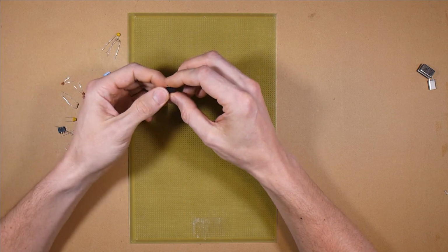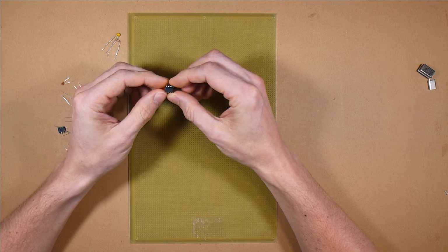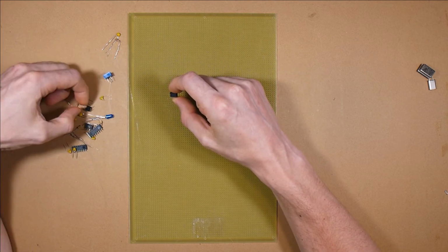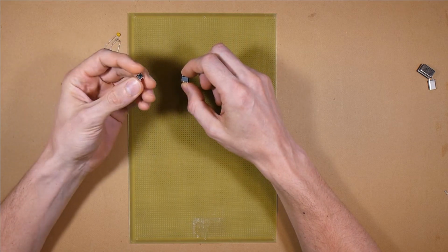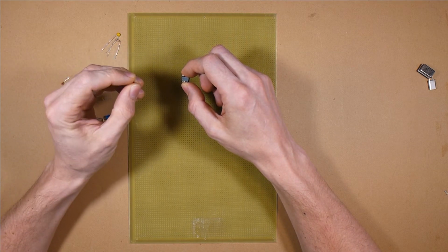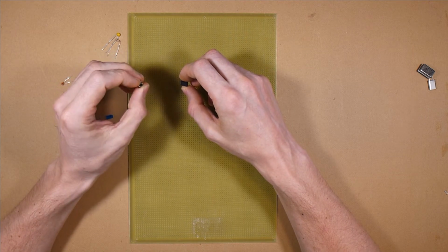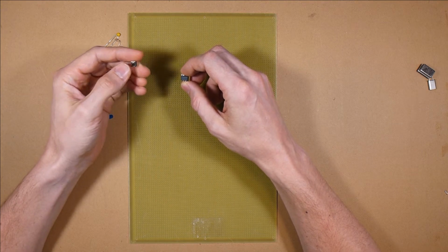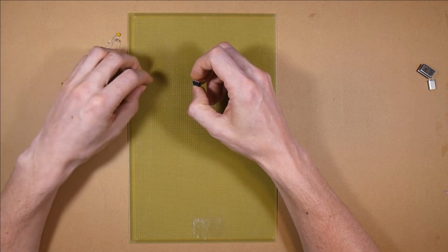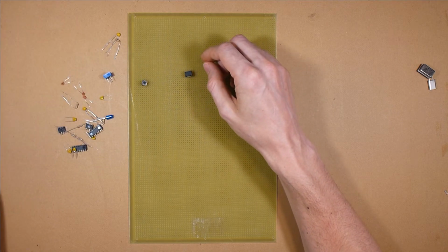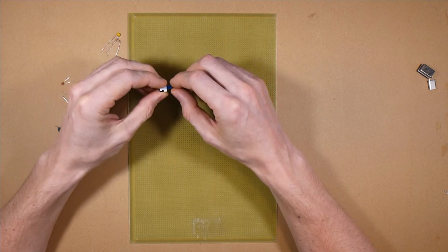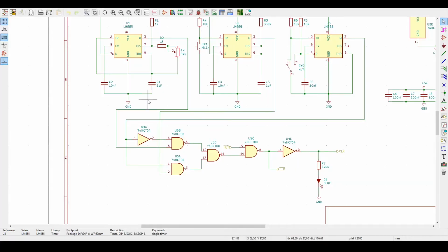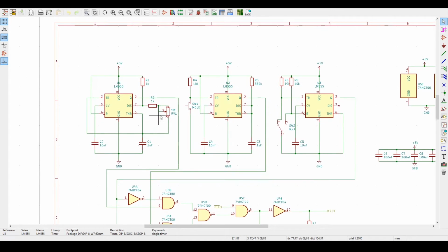Also, with this same IC, we can use it to make a debouncer in order to get our manual clock pulses, to advance the clock manually and debug some program or just go even slower than the clock can. And also a debouncer for the manual automatic clock switch. So we'll just go through the schematics for the clock module a bit.